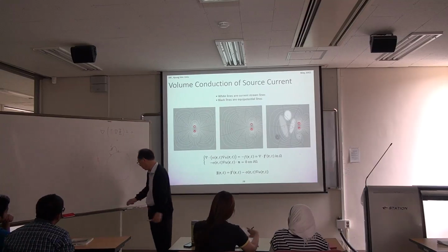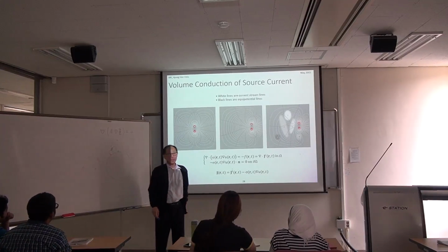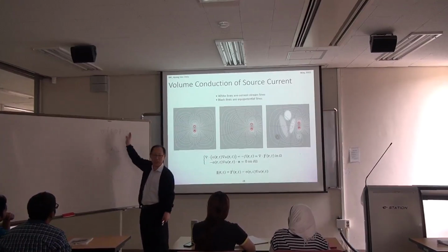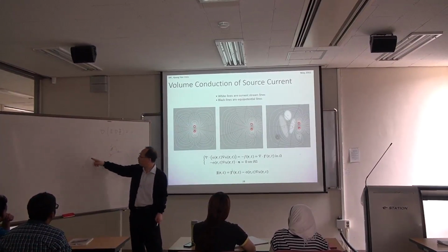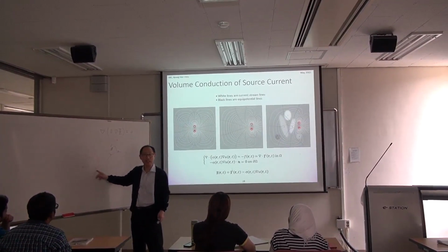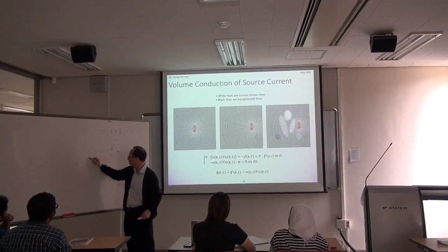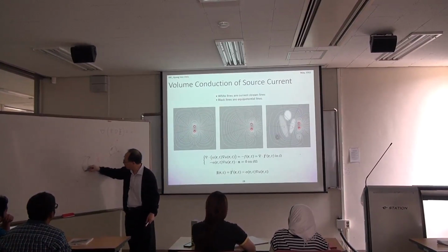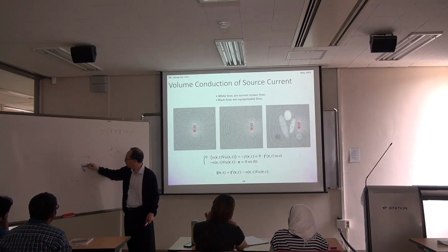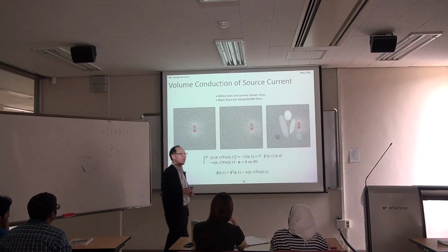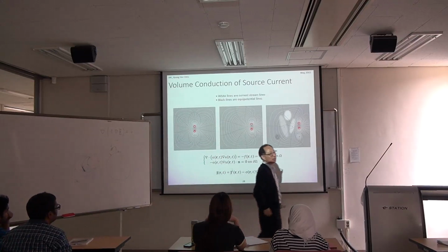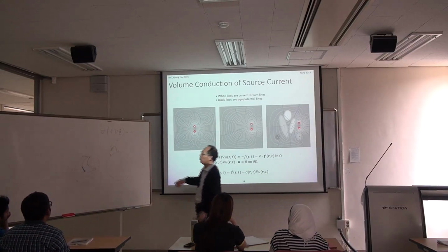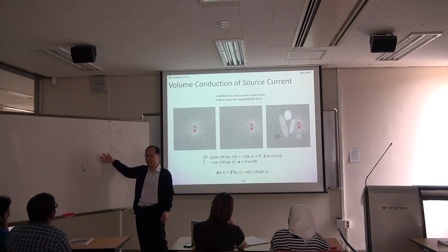How do you find the lead vector in this case? We have to solve this equation again using injection current here and here. And that will give us this kind of injection, and then we are going to have a lead vector shown here, and this vector and this vector should be multiplied as the inner product. That will give us voltage.